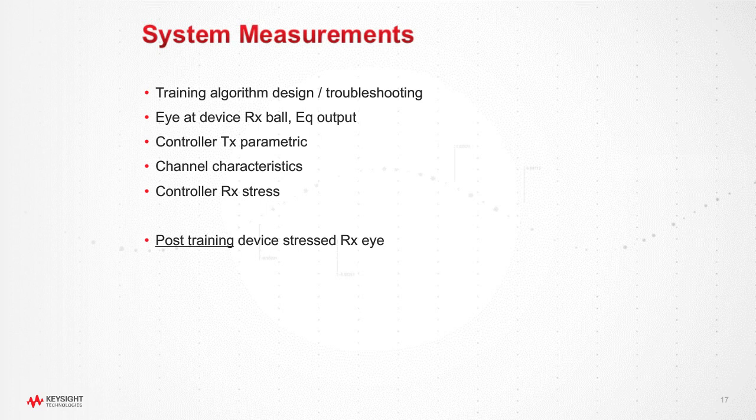That's the controlled impedance buffers. DDR2, 3, 4, every time we've upped the speed, there's been additional training sequences required. Those are basically search out and optimization algorithms. And when you see something go wrong, it's often because the algorithm made an assumption that's not valid for a particular system that you plugged a memory device into. And troubleshooting that has always been a challenge. That's going to be even more so as the speeds go up.